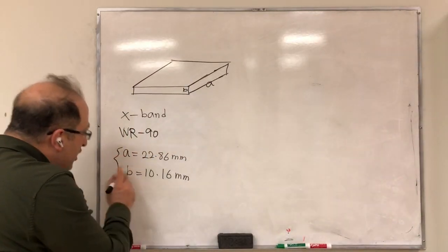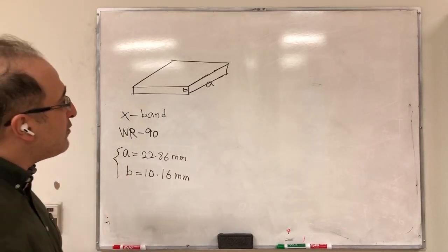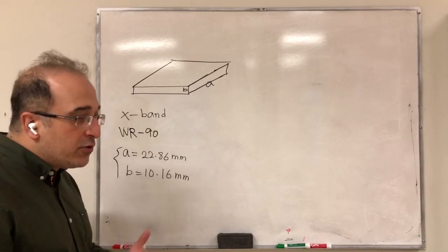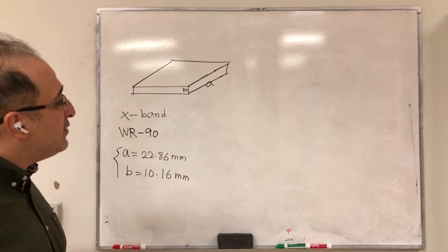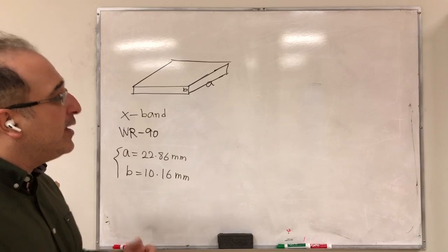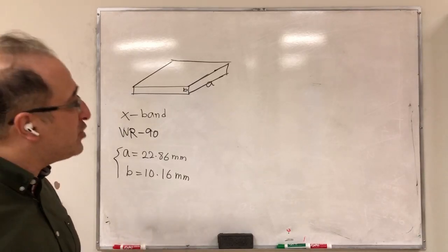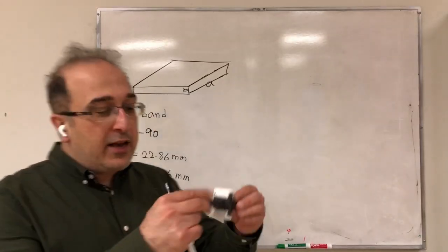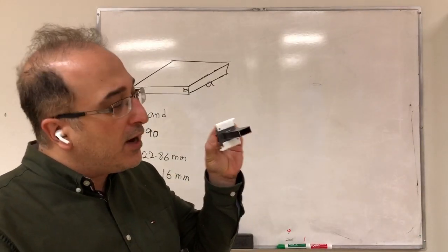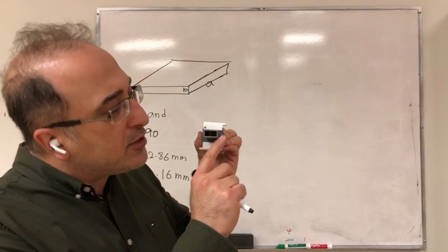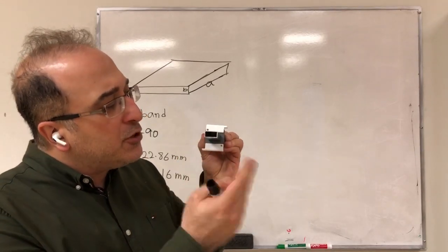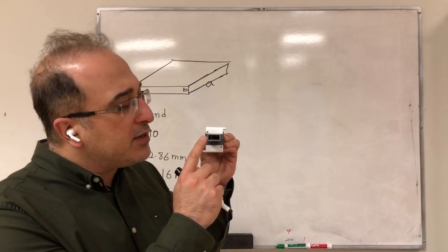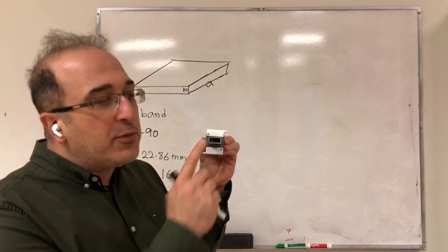So essentially, you know the cross section that you have, and based on the previous lecture, we saw that we have about 3.5 dB directivity. Now, if you want to have more directivity, we said we can increase the aperture size by going to the horn antenna. So here I have an open-ended waveguide antenna. You see the size of the aperture is here. As you learned, A is at the center frequency about 2 lambda divided by 3, and B is about lambda divided by 3.